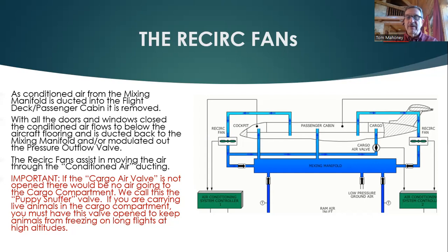And important, as we talked about before, if the cargo air valve is not open, there would be no air going to the cargo compartment. We call this the puppy snuffer. And if you are carrying live animals in the cargo compartment, you must have this valve open to keep the animals from freezing on long flights at high altitudes.